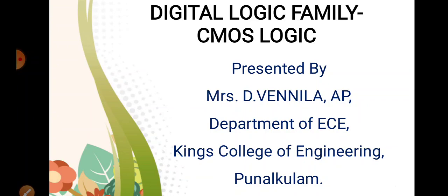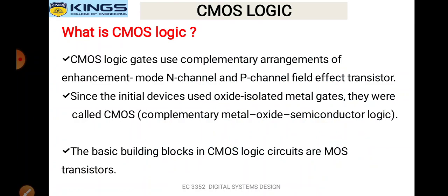Today we are going to discuss the topic CMOS Logic, which is in the digital logic family. What is CMOS Logic? CMOS logic gates use complementary arrangements of enhancement mode N channel and P channel field effect transistors. Since the initial devices used oxide isolated metal gates, they were called CMOS. CMOS is nothing but Complementary Metal Oxide Semiconductor logic.